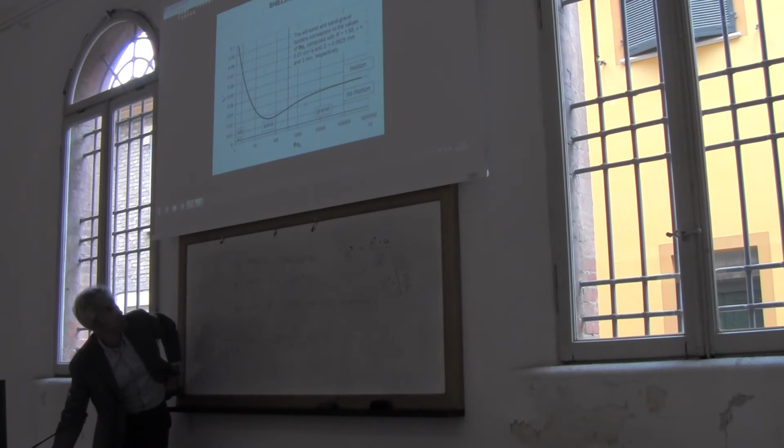When we design, what we usually do is refer to turbulent conditions, and we take the value of the Shields parameter, 0.03. Okay, so given this number, 0.03, we can estimate directly. And then we check.